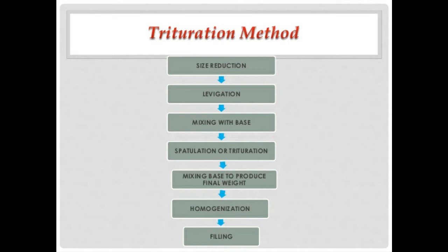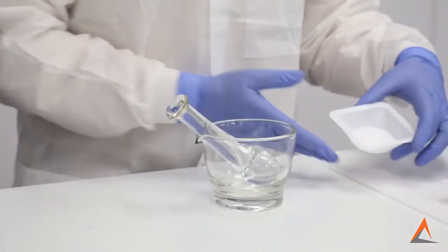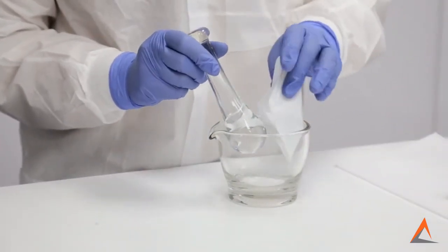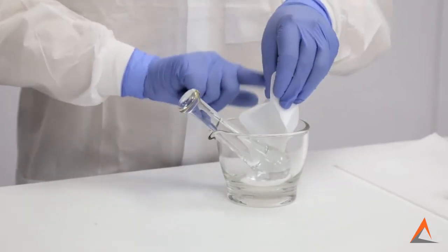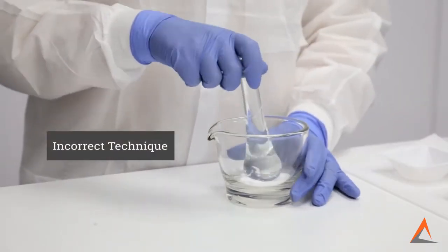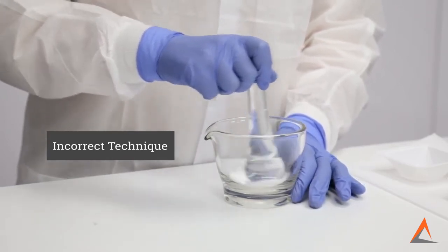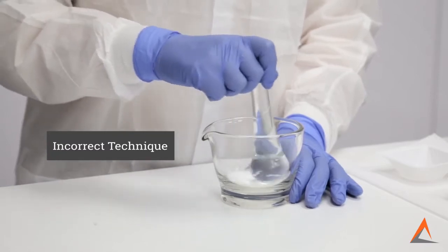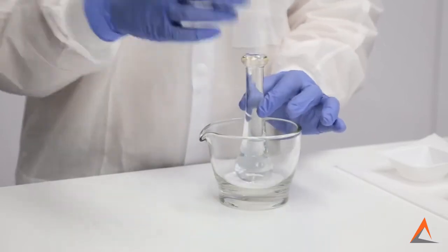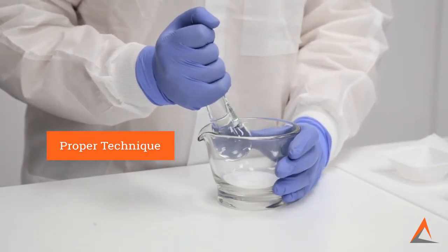Size reduction is commonly used in pharmaceutical industries because it increases the surface area in most reactions involving solid particles. The rate of reaction is directly proportional to the area of contact with the second phase. Next, it breaks a material into very small particles in order to separate the valuable amongst the two constituents, to achieve intimate mixing, to dispose of solid wastes easily, to improve the handling characteristics, and finally to mix solid particles more intimately.